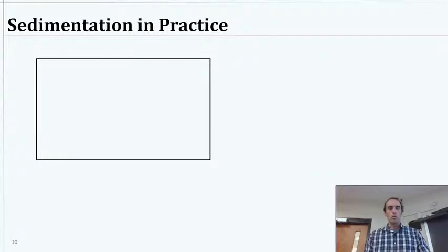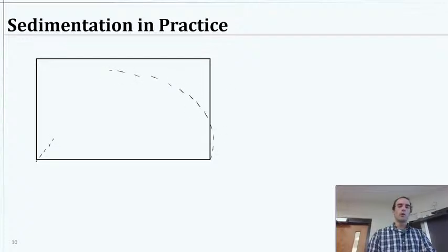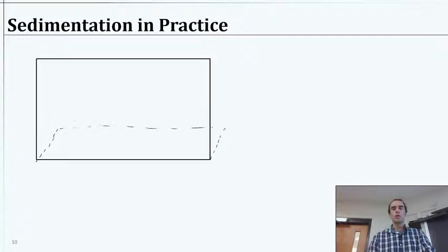Okay, so there's one other concept I want to introduce here, and that is how do we connect our critical settling velocity to the actual design of the reactor. Okay, so in reality, we'll have some reactor, and it could be a circular one, or it could just be a rectangular one where we'll draw it and say this has 3 dimensions, the length, a width, and a height.